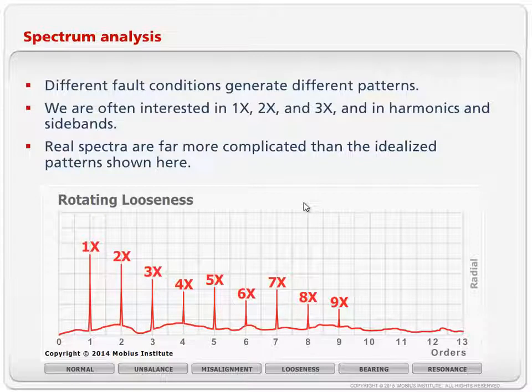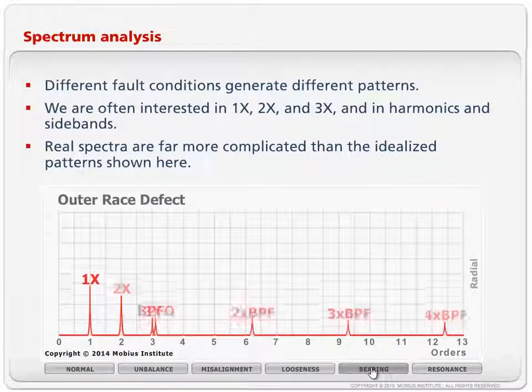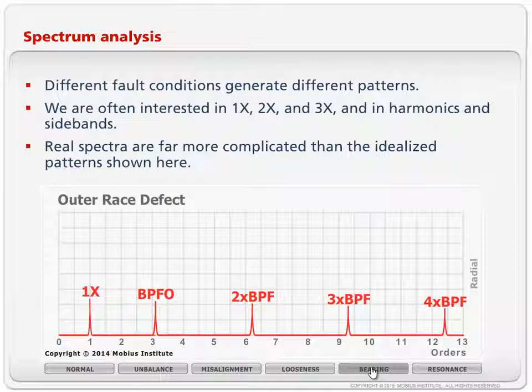And if you understand why the vibration changes the way it does, then not only do you make sure that you set up the analyzer to capture that vibration and you take measurements in locations that will capture it, when you see patterns like this or patterns like that or patterns like this for bearings, you won't just think of the wall chart, you'll think, aha, harmonics, what does that tell me? Sidebands, what would that tell me? Lots of peaks, high amplitude, low amplitude, all these patterns should tell you what must be happening inside the machine in order to create those patterns.